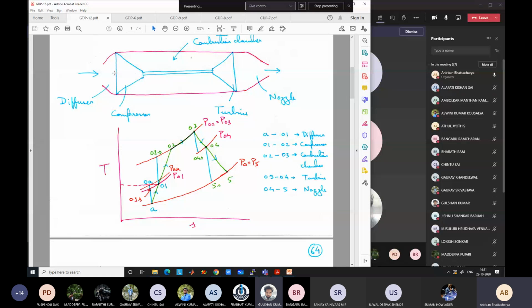What will change if there is huge frictional loss? Temperature, sir. Pressure. Pressure loss. Temperature cannot change. Pressure loss. What I am saying is that frictional loss itself is again contributing back to temperature. Whatever energy is lost is again manifested as temperature. Temperature cannot change. Pressure loss will be there, right? Right. So there will be pressure loss because of friction.